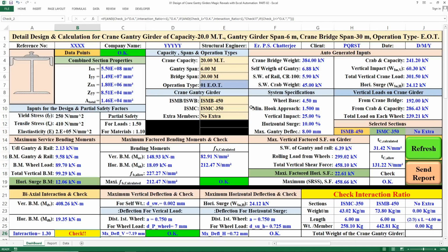Why? Because structural engineering is about balance, not just adding more steel. A heavier channel shifts the center of gravity and increases the dead load. If the section becomes too top-heavy, the gain in strength is swallowed up by the shift in the neutral axis. To fix this, you move back to the ISMC 300.